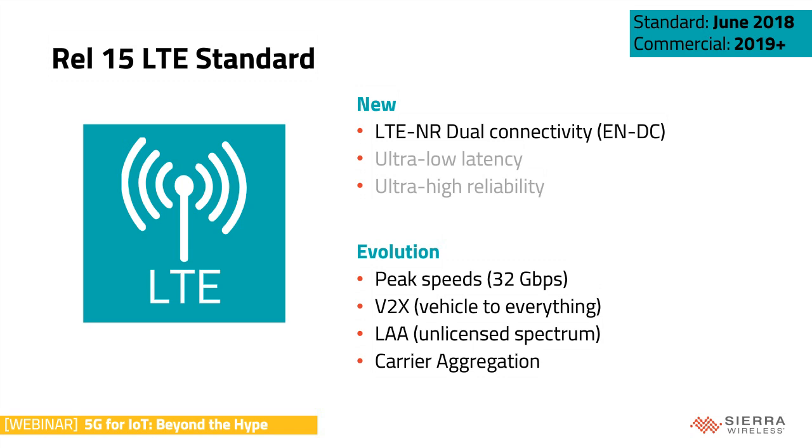The new ultra-low latency feature, which is new in Release 15, is designed to significantly reduce latency, unsurprisingly. It's very significant. The latency can go down to about 1 millisecond from today's theoretical 15. So this is enough to meet the 5G latency requirement of sub 1 millisecond. However, this feature requires significant, very low-level changes to LTE, and so the commercialization at this point is a bit questionable, which is why I put it in gray there.